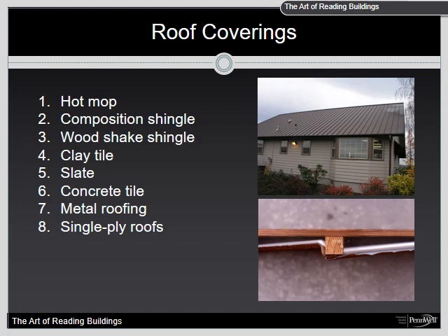The disadvantage, obviously, is these things weigh a ton, so it's going to dramatically increase the dead load on the roof. And if you have lightweight trusses underneath them, it may make them prone to failure even quicker than anticipated. Also, ventilation is going to be a nightmare because these things are well seated and extremely heavy, so trying to get through them can be a problem. And then, of course, an even bigger problem is individuals on the ground with these flying clay tiles coming at their heads. So that can indeed be a problem.